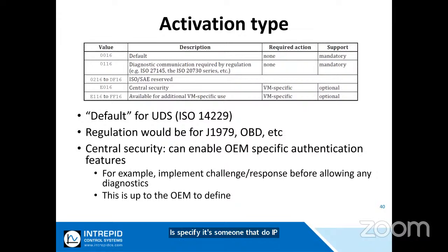Yes. Okay. So Bill, a good question. Is it specified somewhere that DoIP diagnostics is over TCP, or is it open to utilize UDS? After activation, all those diagnostics are under two different protocols. Either it's TCP or TLS, which is really going to be TCP underneath, because TLS is a security protocol. But it is correct that, as far as I know, and I did read through the latest spec again this morning, TCP is the only method by which we're connecting in Ethernet using the IP suite. Okay.